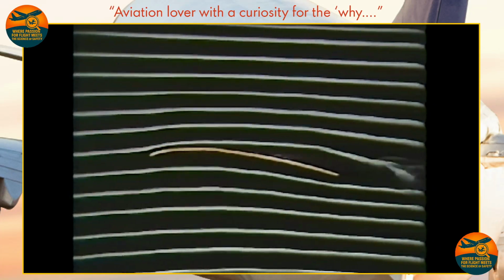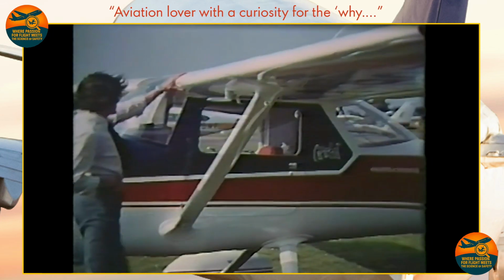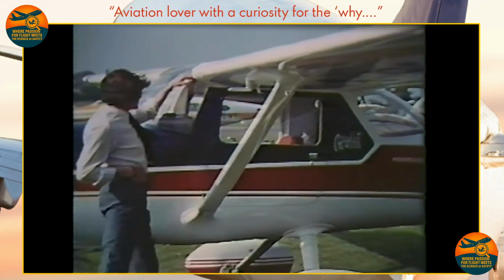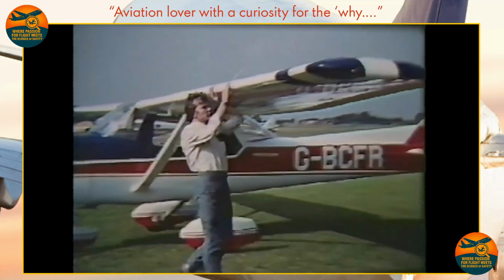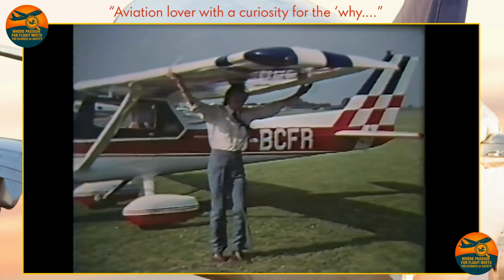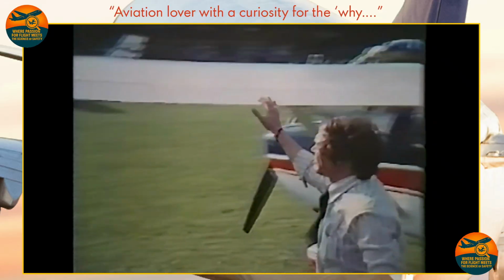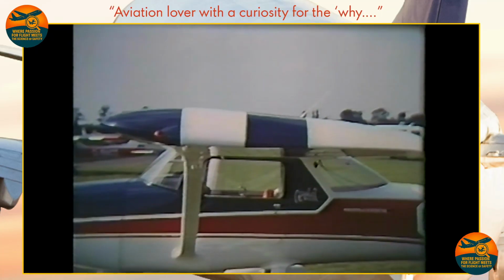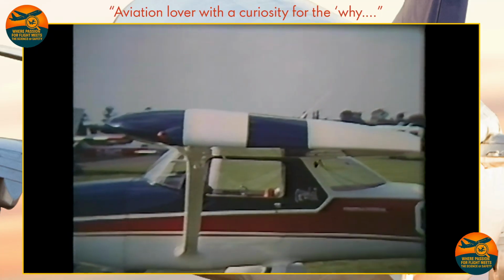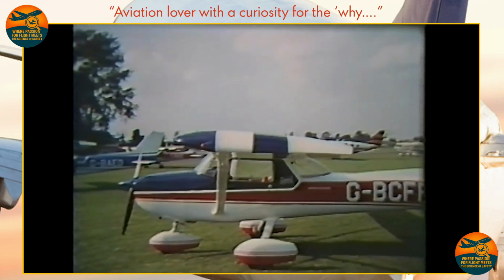But if we look at the wing itself, we find that it's neither a flat plate nor a curved plate, but a combination of the two. It has thickness. The underside is almost flat. The leading edge is blunt and rounded, while the trailing edge is sharp. The upper surface is curved or cambered, and the wing is in fact attached to the fuselage at a slight angle to the horizontal. Cut a section through the wing, and it looks like this.